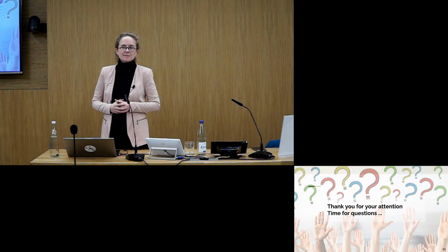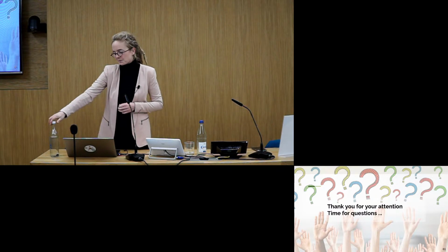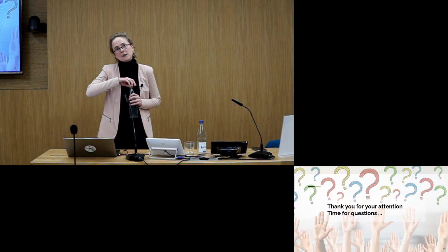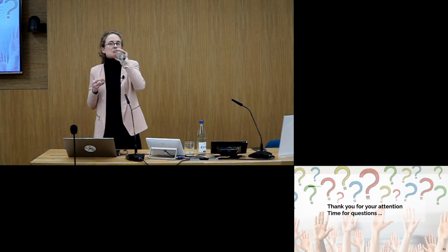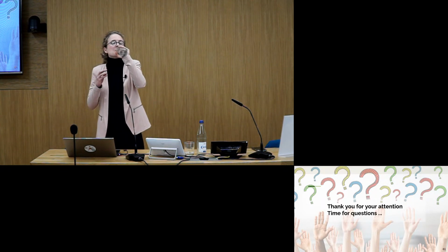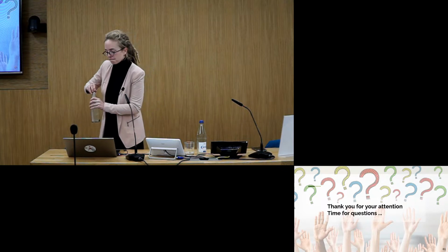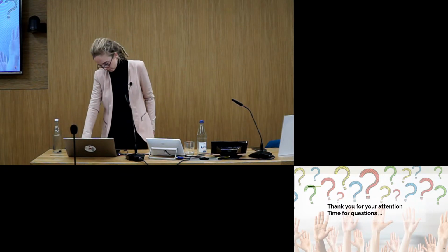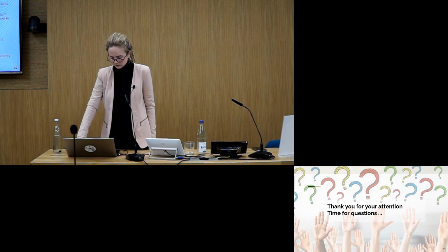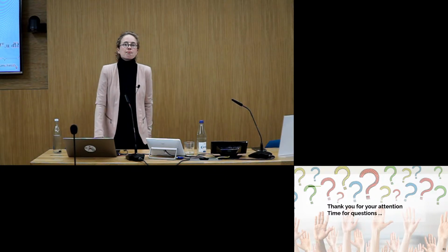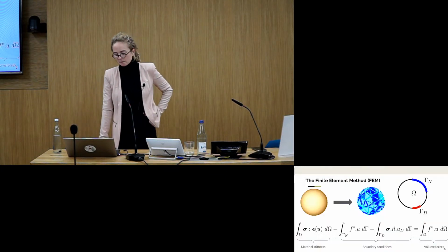Second question. At the very beginning of your presentation, you showed the equilibrium equation for solid mechanics, and you said I'm trying to solve this equation. But you showed the equation in a small strain framework. But if I didn't understand well, finally you solved large strain problems, didn't you?